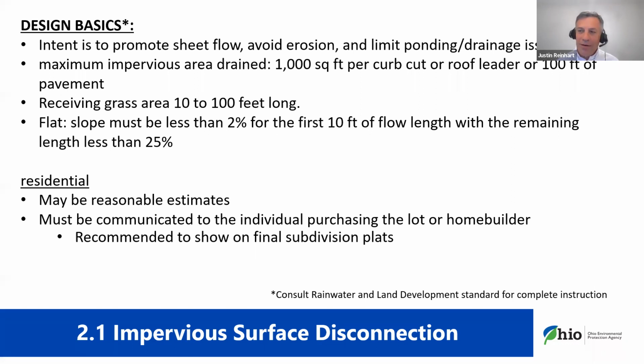They need to be flat, and this is sort of contradictory to our drainage principles of let's move water. Well, we want to move water just slowly, so there's a stipulation in here to have that first 10 feet flat before we start to send water away at a steeper slope. We'll see. This is probably one of the sticking points, and because it so defies some of our traditional grading, how we can make this work, if there's an improvement to be had here for some adjustments in the future. But again, the point here is to make sure that we actually have a sheet flow scenario.